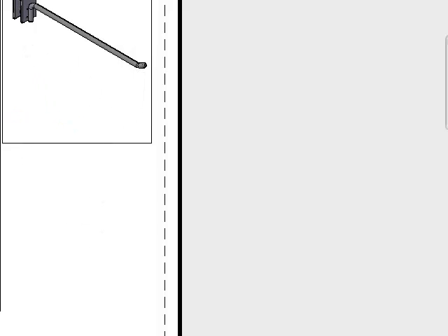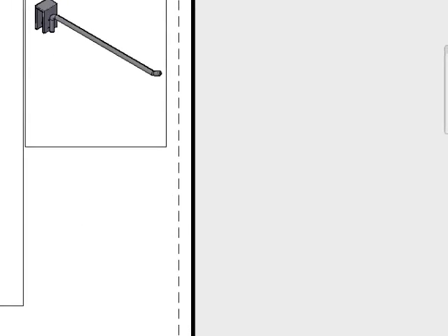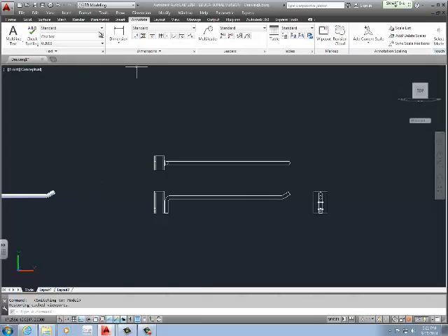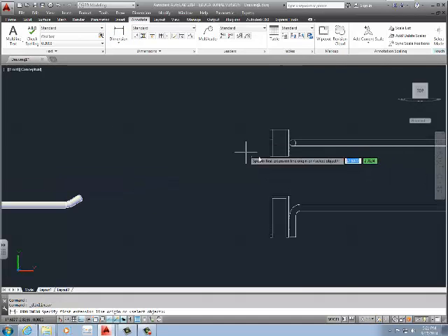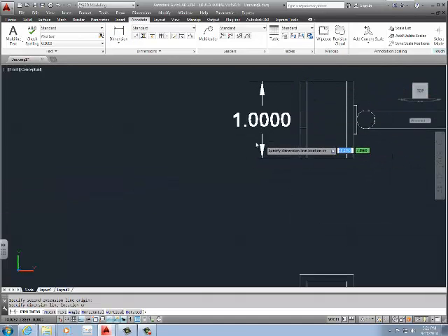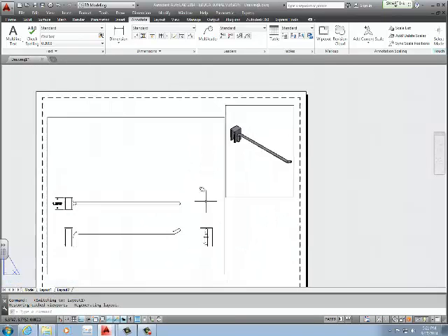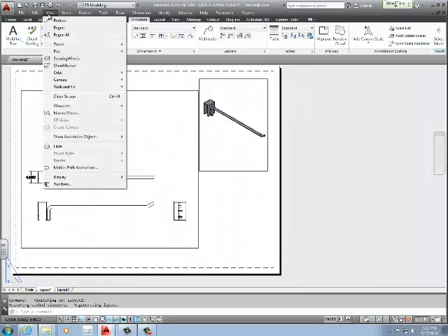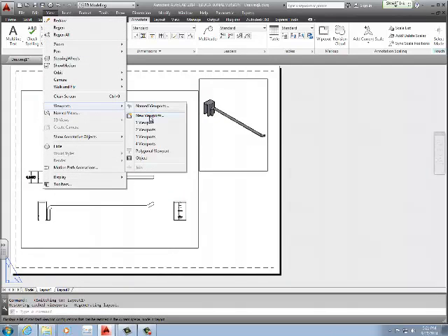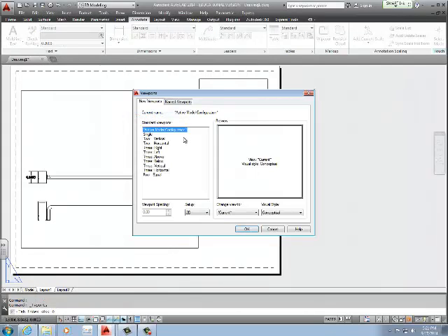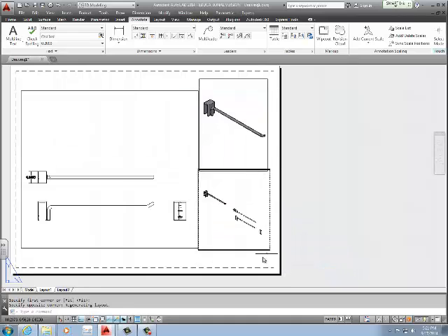For the 2D parts, technically I should already have dimensions in here. In the actual model space, I can at least add a thickness of one for the wire for reference. At this point, I'm just going to put in 0.3. And if you guys have problems with creating viewports, go to View, Viewports, New Viewports. That didn't quite work. You can go with the model configuration, or you can go with the single. Click OK, and you just create a box.